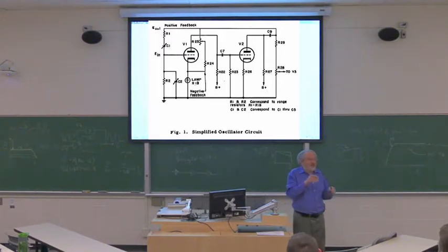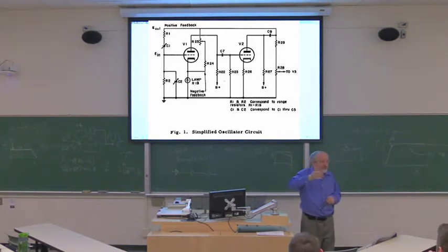Any other opinions? Did you ever try to measure a light bulb with an ohm meter? So, okay, if you try, the bulb which says on it 120 watt, which means 1 amp, which should read 120 ohms, reads like 30 ohms. Because it's only 120 ohms when it's hot, when it glows. But when it's cold, it's much, much less, because it heats up to 2000 degrees, right? So the change is huge in resistance.